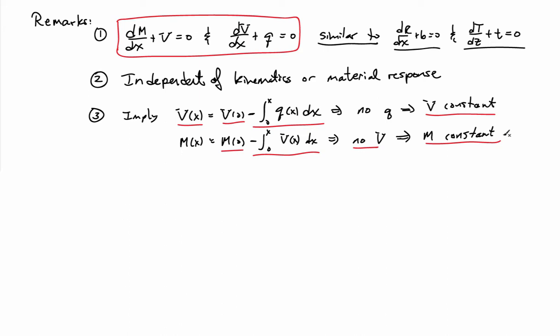And again, we also have this relationship that if you know the polynomial order of the shear forces, then the moments are one polynomial order higher than that. So it's a useful thing to remember. It can help in checking results when you're doing calculations.